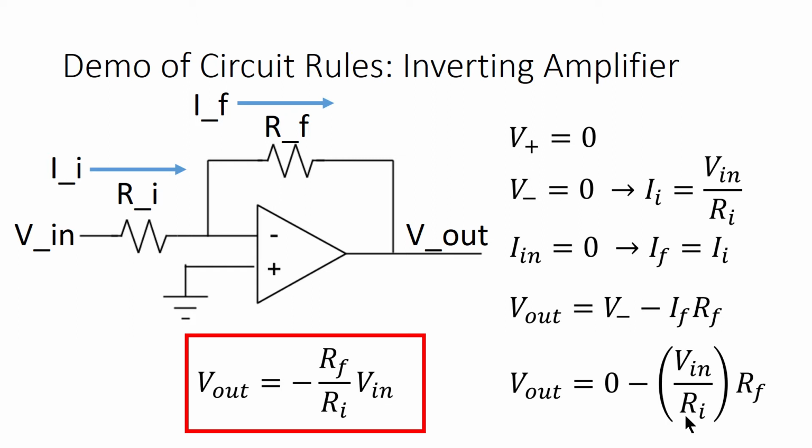We'll have a whole video about op-amp power supplies later, but note that this op-amp would work really poorly if the negative power supply was at ground, because V out couldn't ever reach the value it was aiming for. It would just rail out at ground.